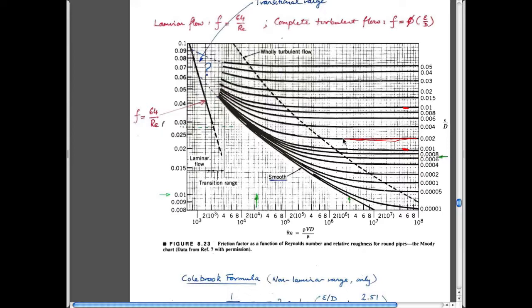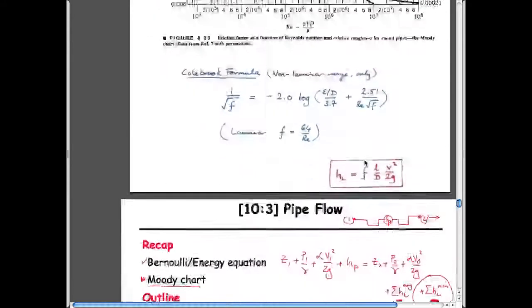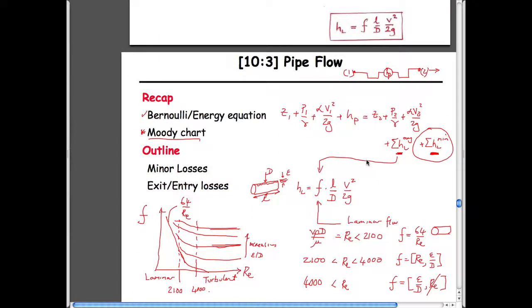And so also for flow in a pipe, if you're beyond this demarcation here into fully turbulent, the magnitude of the friction factor is always constant. It needs to get above this threshold before it's constant, so you need to know that Reynolds number. But once you're on the right-hand side of this, it's always the same magnitude of friction coefficient, which makes it a little simpler because you have to solve this equation.